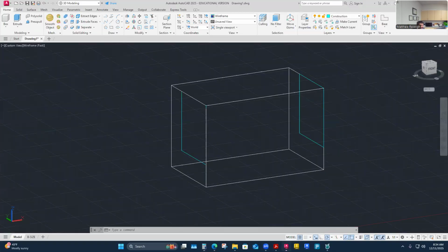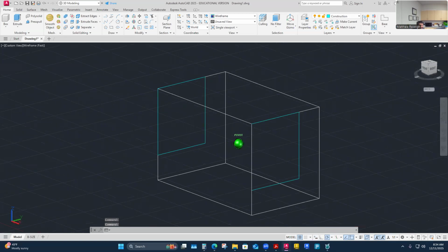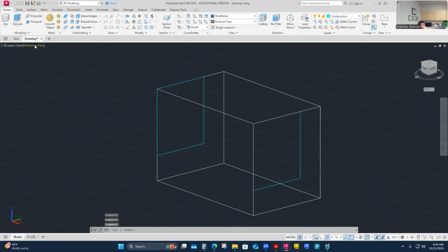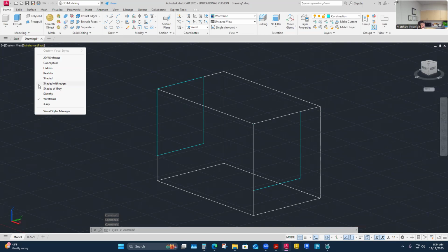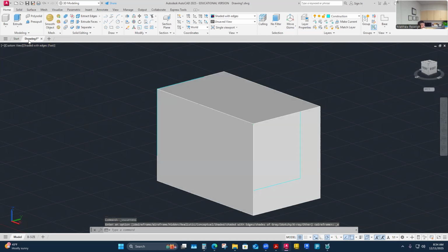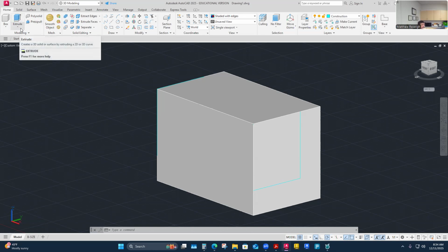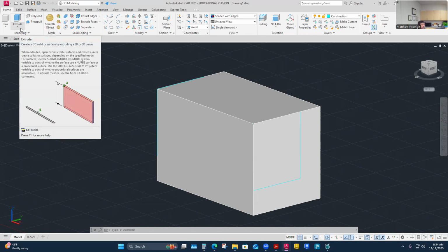So let's do that. I'll press pull this thing. And this one I'll see how it's drawing easier with the 3D on. If I'm going to do a press pull, or you could do an extrude, right? Really similar features here between extrude and press pull. In Inventor, I don't think we have press pull. In Inventor, we'll always go to extrude. Extrude is either a cut or a solid in Inventor.